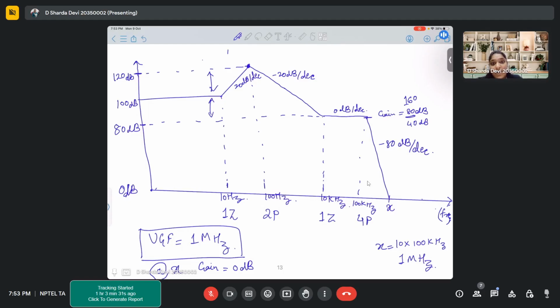And in Bode plot, majority of the times you draw the Bode plot for the stable systems. But here, let's say you have a pole at positive S and at the negative S also. Bode plot does not define two frequencies, positive and negative, right? So you will place it at the same point, but the system is already unstable.